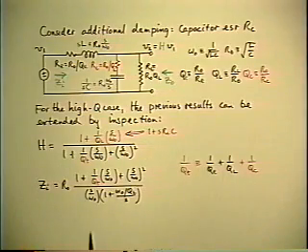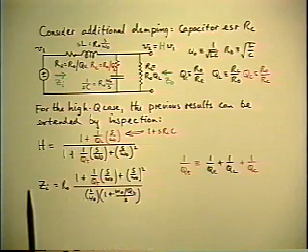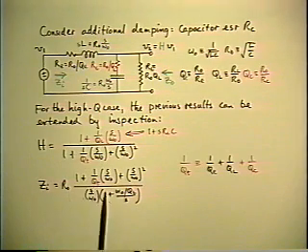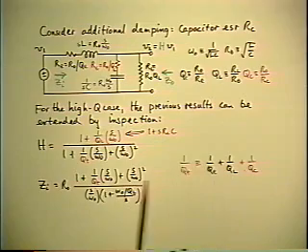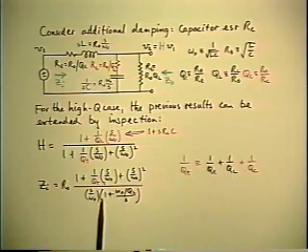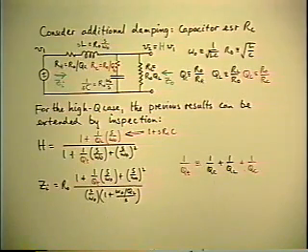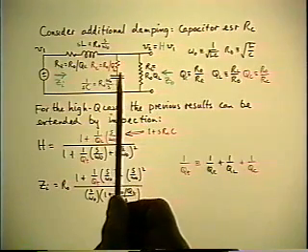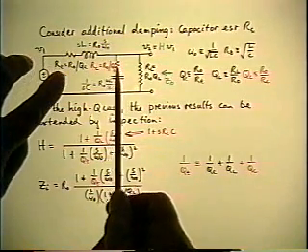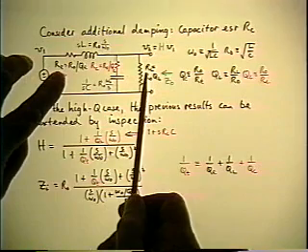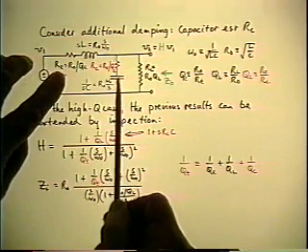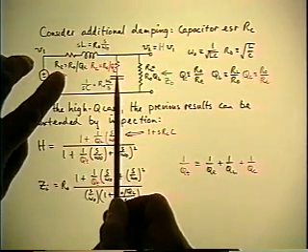Okay, you can do the same thing, of course, for input impedance. Neglect second order effects. The total Q factor, again, will be the triple parallel combination. Look for new corner frequencies. At zero frequency, the input impedance is dominated by the RL. Capacitor is open, makes no difference whether the RC is there or not.